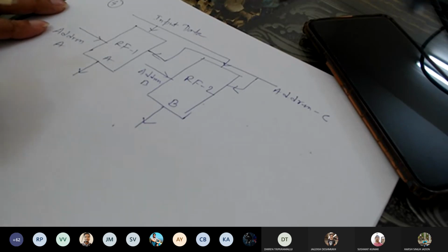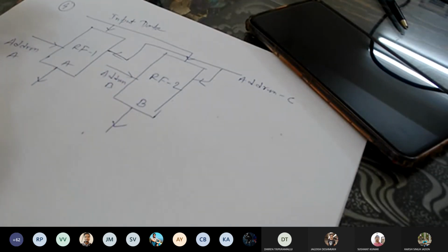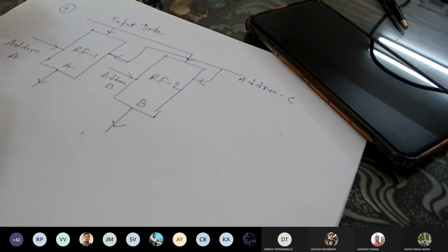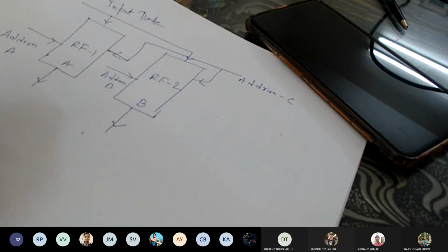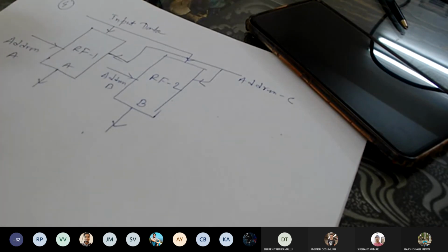Now I assume that you have a circuit to do the transfer from one register to another register, which we have probably understood in one of the labs. With that concept, you can actually design the register file for the whole 32-bit system, and that will be used as a library for larger, bigger projects.